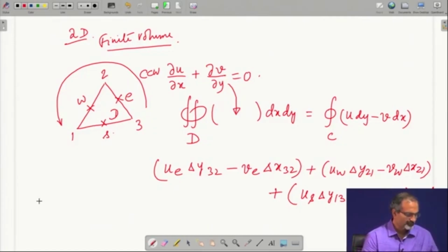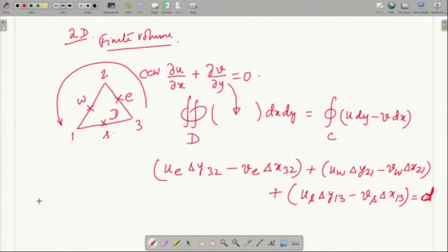So, we have different means by which we can do the calculations in the unstructured domain, and you remember that in the viscous terms you will see second order derivatives like this. So, when you apply the surface integral on them, they will convert to line integrals involving first order derivatives. So, you also have to find out means by which you can define first order derivatives at these control points.